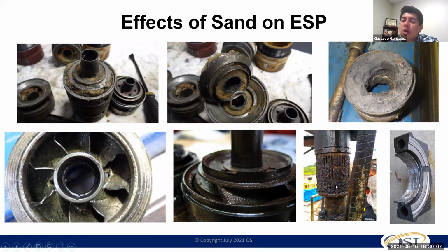But when you're dealing with new wells, just to be more proactive, we always recommend removing it, increasing the open area, reducing the pressure drop, and being able to have a better ingestion of sand. Because this open area is not going to be enough, at that point you can face some plugging, as you're able to see right now.